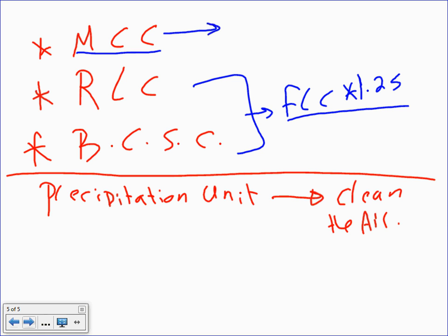They pass the air through a filter first that charges the particles positively. If you look at page 178, it's very clear. They have a filter called the ionizer. They blow the air through this ionizer inside the unit. The ionizer charges every little particle in the air. It gives it a positive charge, and it moves it towards the collector cells. Can you see the collector cells, which are negatively charged? That's easy, through battery or rectification. So now all these flying particles in the air that could hurt me, or any of those workers, are positively charged and pushed toward filters that are negatively charged.